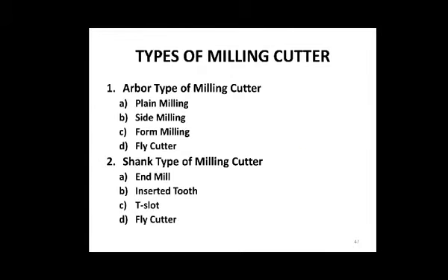In the early 1990s, the use of coatings to reduce wear and friction became more common. Most of the coatings are referred to by their chemical composition, such as TiN. TiN has a basic yellowish coating and that has fallen out of wide use. Advances in individual coatings are being made, with coatings such as amorphous diamond and nanocomposite PVD coatings beginning to be seen at high-end shops.